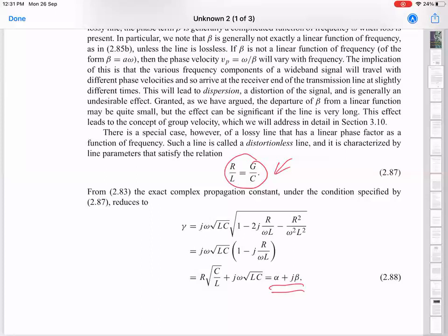But it's already in a heat path, so isn't all the heat that can transfer getting absorbed by the heat path? Yeah, but whatever mechanism is causing the heat to be removed, if you're using, say, liquid helium, then you're going to increase the boil-off rate of liquid helium unnecessarily. Okay. Or if you're using some other kind of technology, at some point it will not be able to keep up.